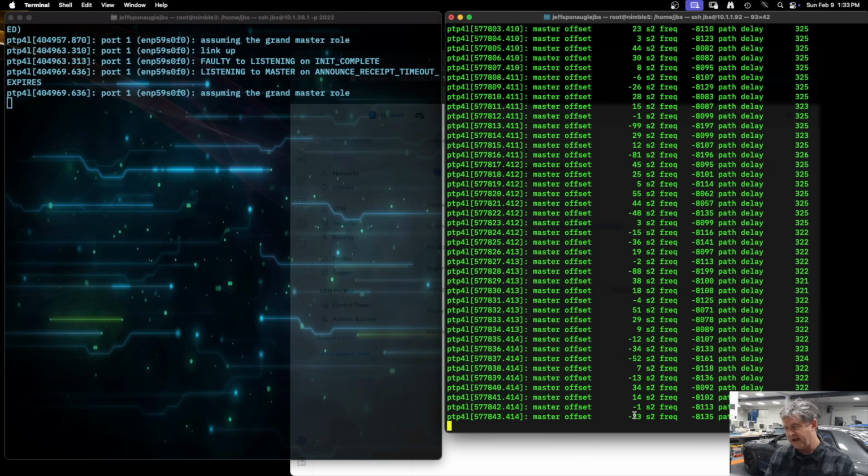And it tells you here the error, this plus or minus here, is the error in nanoseconds between each one of its measurements. And then it's slowly tweaking the clock offset to try to keep it in sync as possible. And it is generally within 50 or 60, 70 nanoseconds. I think the average ends up being maybe 25 when I let it run for a little while, with occasional jumps of 60 or 70. You can see one there, minus 67. But certainly well within the range of the couple hundred nanoseconds that we're looking for.